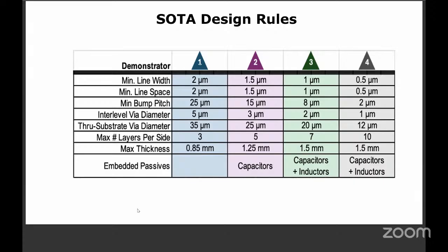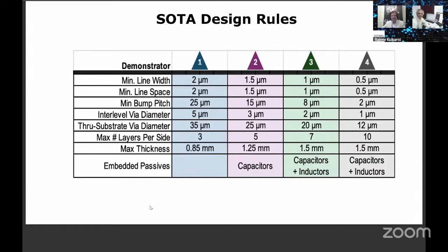Technology level 2 is 1.25 mm. Then finally, at technology level 3 and 4, we are hitting a classical 1.6 millimeter PCB thickness. The key here is your Ultra HDI may coexist with some of the earlier PCB technologies. They may coexist in the same PCB layout, in the same PCB outline. Interesting, very interesting.